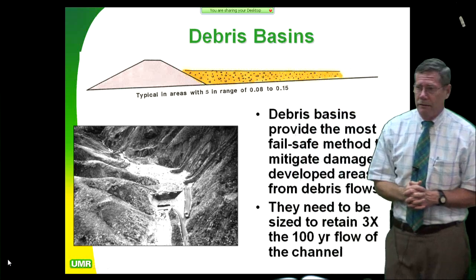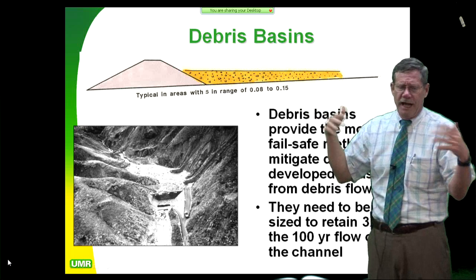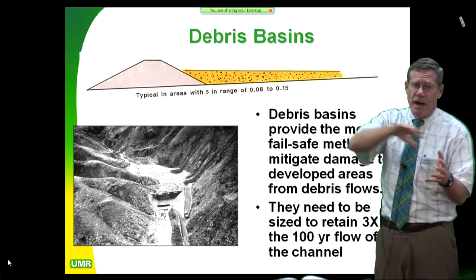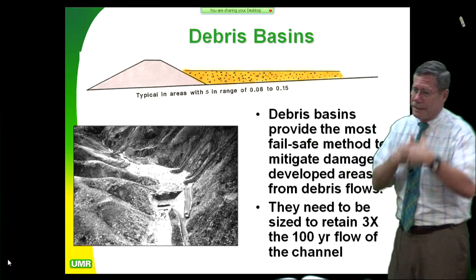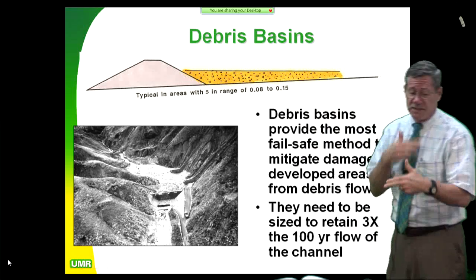Now that's what happened in La Crescenta last spring. But every time it rained, their basin filled. And they had hydrophobic soils from having the fire just a few months earlier. So they had to go out and muck it out right away. They'd have 2 or 3 days, muck it out, 100,000 yards, come out, and then next storm, fill it up again. So they were just fighting it.